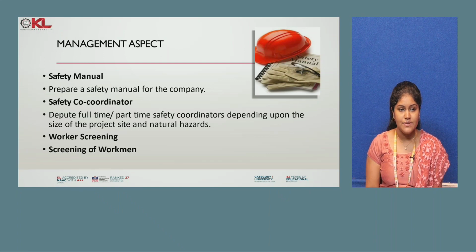Coming to the management aspect, safety manual: prepare a safety manual for the company. Safety coordinator: depute full-time or part-time safety coordinators depending upon the size of the project site and natural hazard. Then screening of workmen. So in the management, proper manuals dealing with safety have to be given, and a full-time or part-time safety coordinator should be there to monitor it properly. Then we have to give the screening for the workmen.